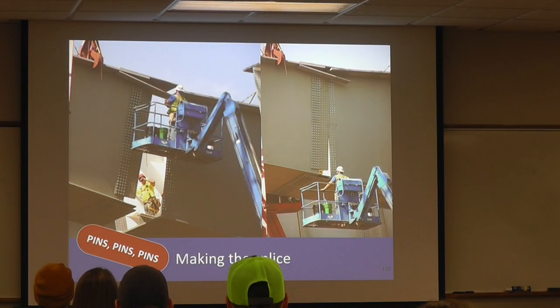So you can see here they bring it in from the top down. They've probably got this far end picked up just a little bit so they can slide it in because they already have their sandwich somewhat made here. So you're going to have your field splice plates both on the top of the flange and the bottom of the flange, each flange, right? You can see how it's going to sandwich together. So they're going to kind of finesse that into place.